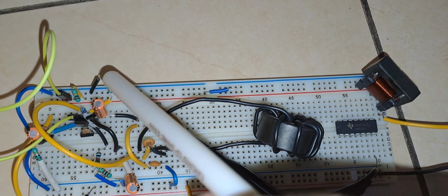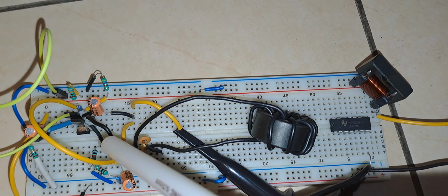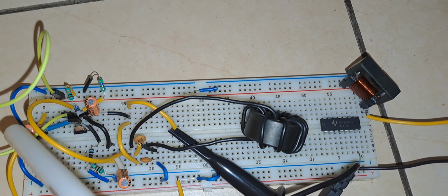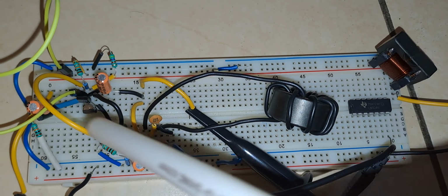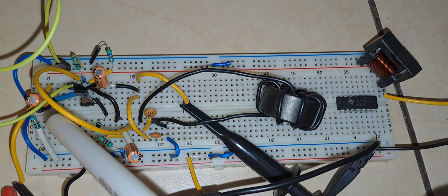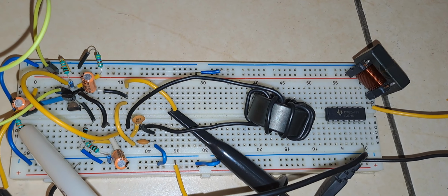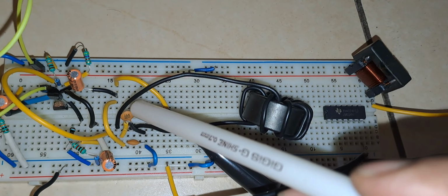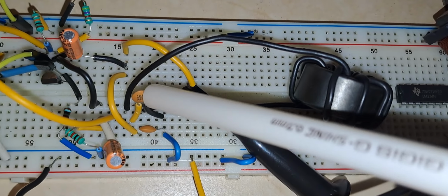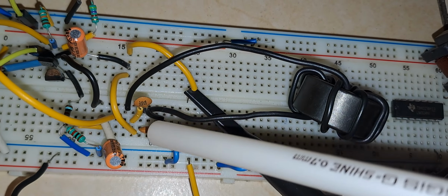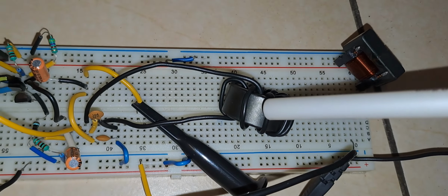These are the biasing resistances, and here also this is the emitter resistance. These three capacitors are the coupling capacitors. And this is the load resistor. The output is taken across this load resistor. Here you can see these are the two capacitors, 0.1 microfarad, 104. So these are the two capacitors, and this is the main oscillator element.